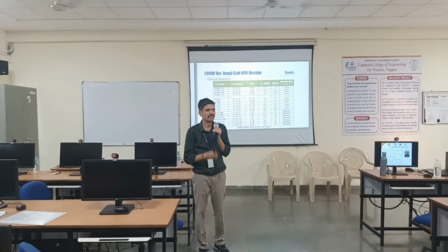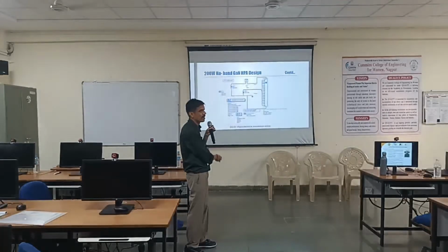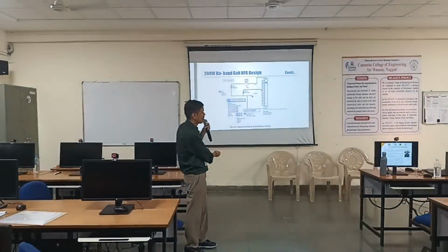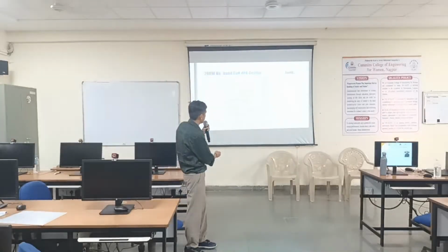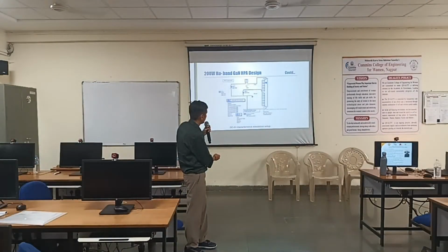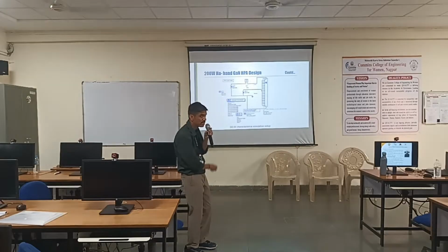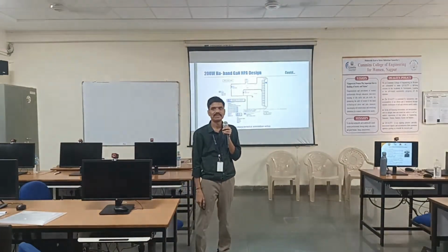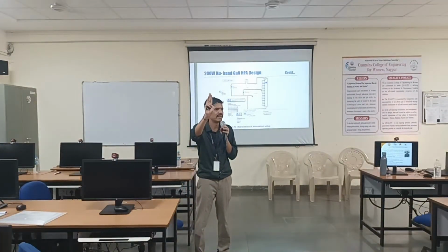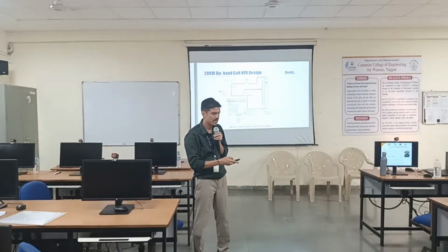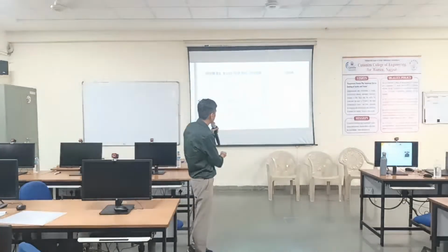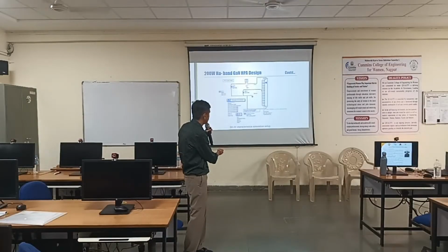We got that model. We started working on that. So we designed the 200 watt. You see how complex the design is. How many gates do you have? You count 1, 2, 3, 4, 5, 6, 7, 8, 9, 10, 11, 12, 13, 14. 16 pins for gate only. A transistor will have 3 pins, gate, drain and source. So they have a model which has 16 gate pins. You have to club all of them together.